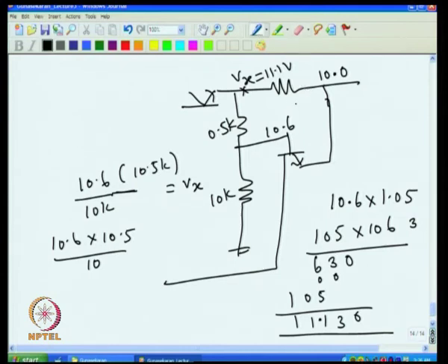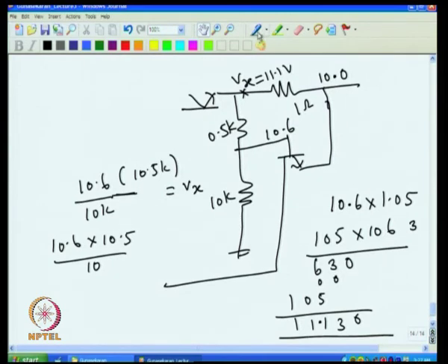Now, if I take the same 1 ohm here, then to get 1.1 volt difference, because this is 10 and this is 11.1, to get a V difference of 1.1 volt, I need a current of 1.1 amps. That means, on a normal condition, it limits the current at 1.1 ampere. Under short circuit condition, it limits the current at 0.7 amps. That is what we had seen in the earlier workout. So, under short circuit condition, we can limit at much lower current than what is available under normal working condition. Now, this is possible because of this voltage division.